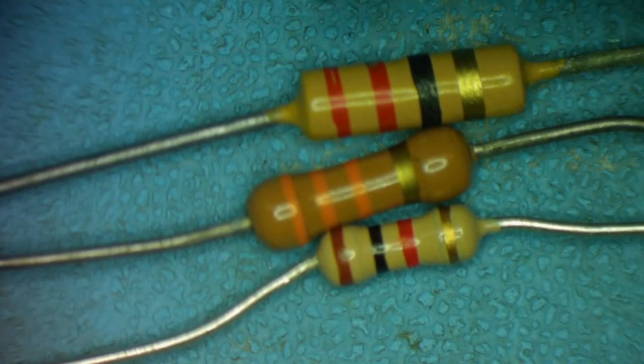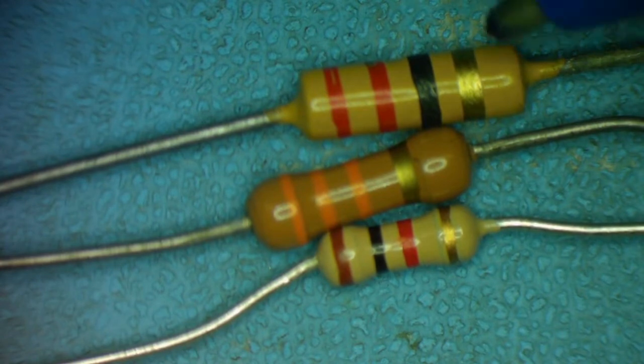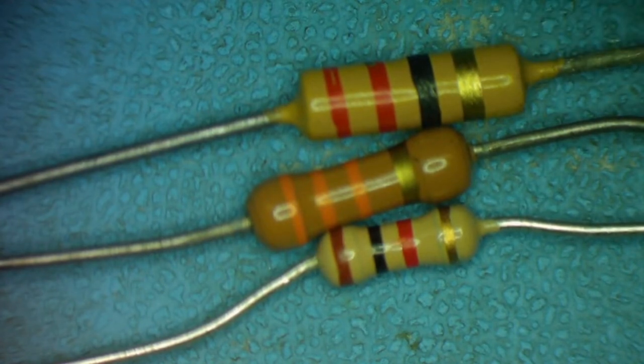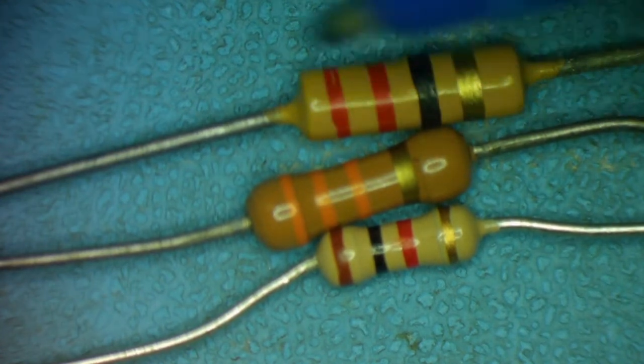Now, we used to learn all this, and you don't need it. But basically, it goes black as 0, brown as 1, red as 2, orange as 3, yellow as 4, green as 5, blue as 6, violet as 7, grey is 8, white is 9, yeah. And then the gold and silver are times 0.1 and 0.01 as a multiplier. So these are 4 codes. So in this case, the gold is actually the tolerance. That's how accurate that resistor is, yeah.